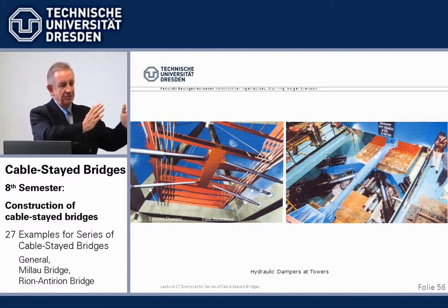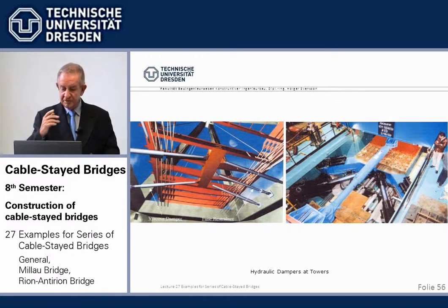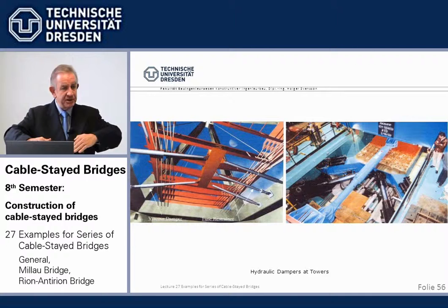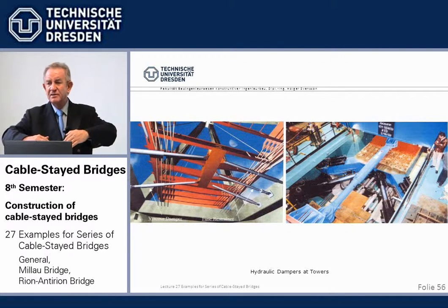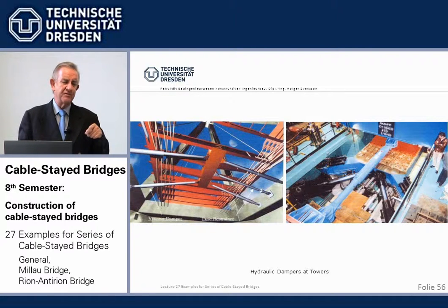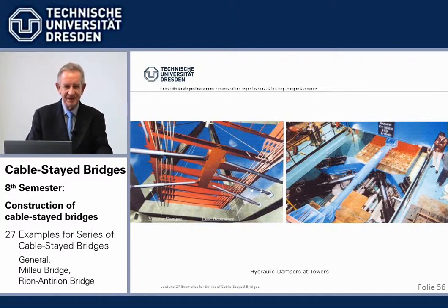Of course, we have 2-meter movement possibilities, movement joints at the end with bumpers. So in longitudinal direction, the beam is free, which gives it a low eigenfrequency, so that it doesn't respond to fast movements of the earthquake when it has this long period. We did this with a desired failure joint for the Pasco-Kennewick Bridge. I told you a long time ago.